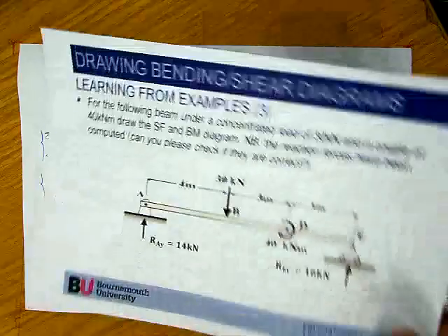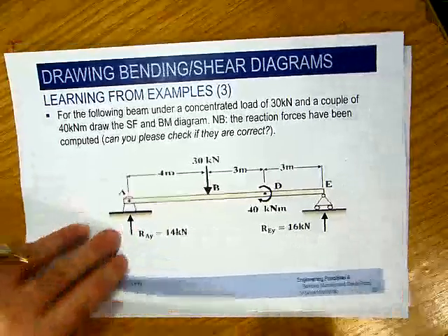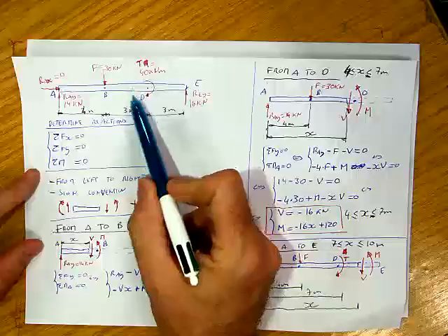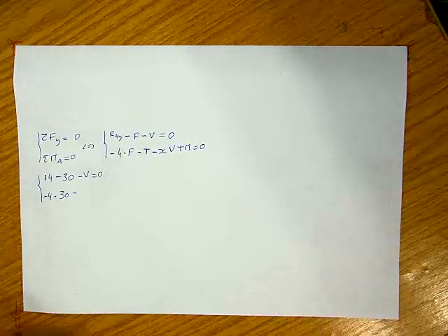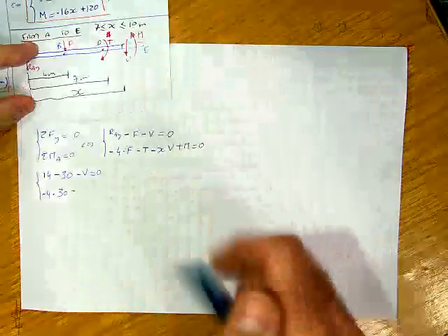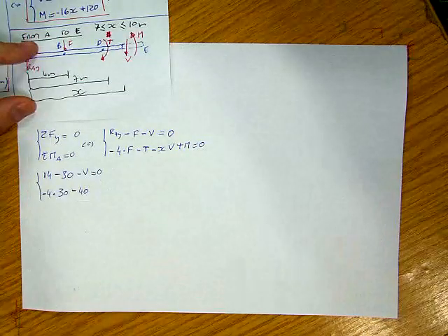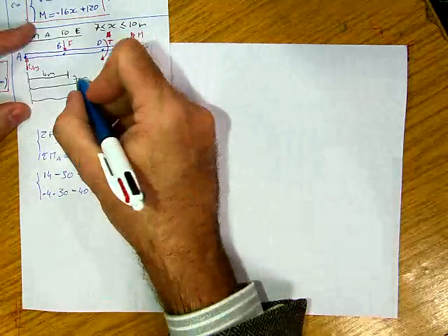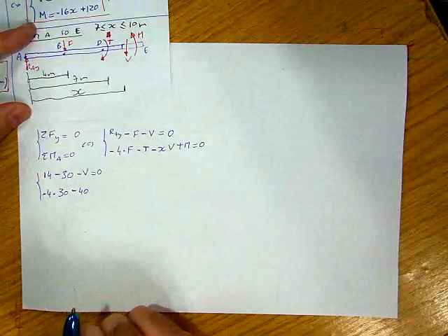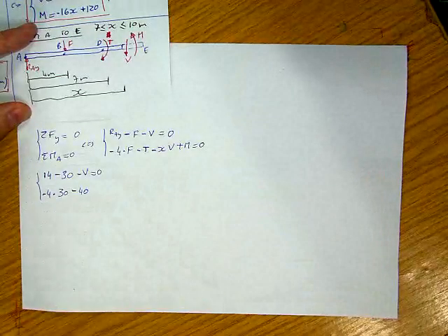I'm going to show you here again. 40 kilonewton meter. And I have also represented that in my original free body diagram over there, 40 kilonewton meter. So I can now basically write minus 40. That's it, because it's a torque or a moment. I don't need to multiply it by any distance. So this distance 7 meters is not relevant because the torques, couples, moments are free vectors.